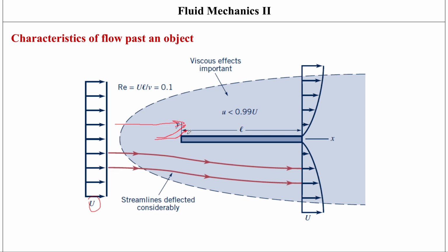So because the layer next to the layer, next to the layer, you've got a situation where the viscous effects are impacting the velocity profile. And now at the end, or some place far away from this plate, you're going to have velocity that is not going to have any effect at all. The velocity is going to be the same here. It's going to be capital U.